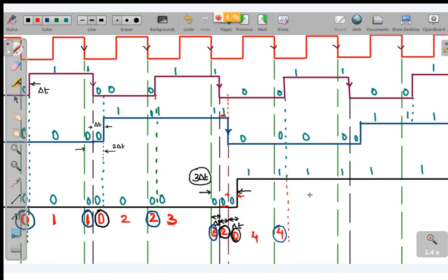So next we have over here 5. And this is also 5. You can see over here, this represents your delay. So delay will be represented with blue color. Next, you can see once again over here, you will be having some kind of glitch. And what will that be? You can see this is 1, 0, 0, and this is 1. So you are getting 4. So 4 is an unexpected state over here. So this is a glitch. This 5 is basically the delay of this, so I have encoded it with blue color.